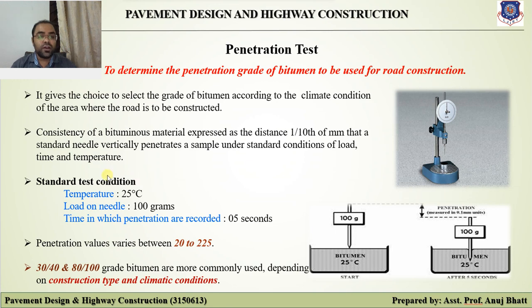So the standard test conditions are: the test temperature should be 25 degrees Celsius, the load on the needle is 100 grams, and the time in which the penetration is recorded is 5 seconds. Here in the figure you can see there is a needle. The specimen should be kept over here and the penetration will be carried out.